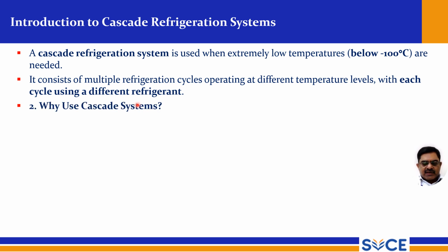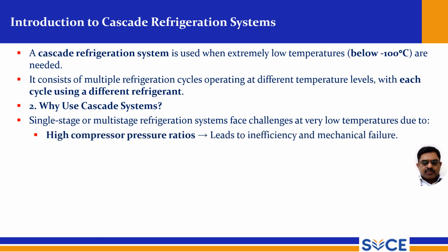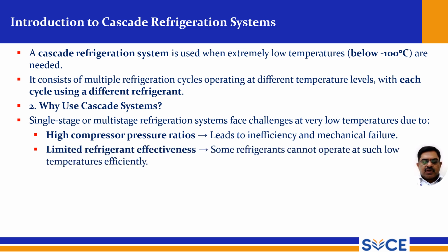So why the cascaded systems? Single stage or multi-stage refrigeration systems face challenges at very low temperatures, due to high compressor pressure ratios that lead to inefficiency and mechanical failure, and limited refrigerant effectiveness. Some refrigerants cannot operate at such low temperatures effectively.